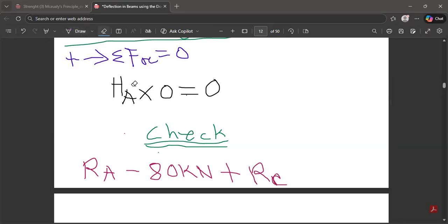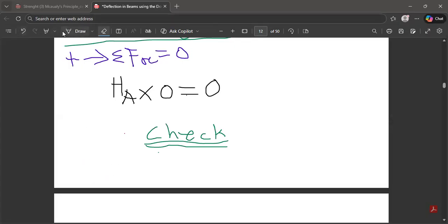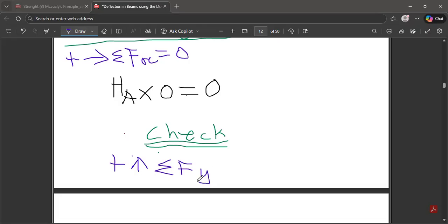But even before that, we have to pull down our rule first. Without the rule, we may confuse the examiner. So in doing so, we are just saying that all the rules are still the same. That is the sum of all forces moving in the vertical direction. If it is moving towards the north, it's definitely going to be positive. At the end of the day, we have to equate all of this to zero.